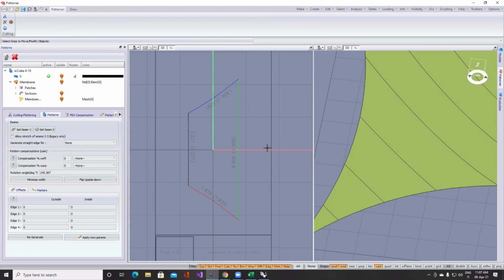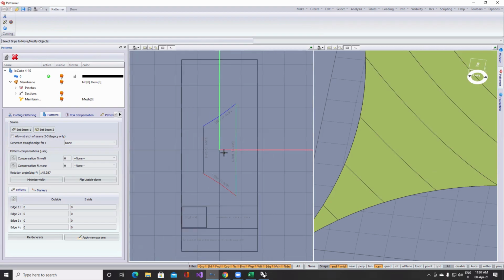If they don't have the same length, I am in trouble when we go to produce this overall object. And they have to be very accurate. Let's say less than 1 millimeter, the length difference of the welding edges should not be more than 1 millimeter, because I am not able to weld them together if there is a mistake in the length of these. Okay.